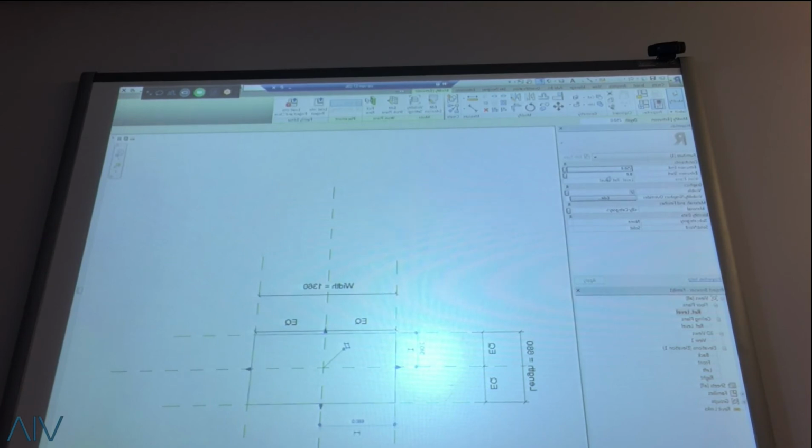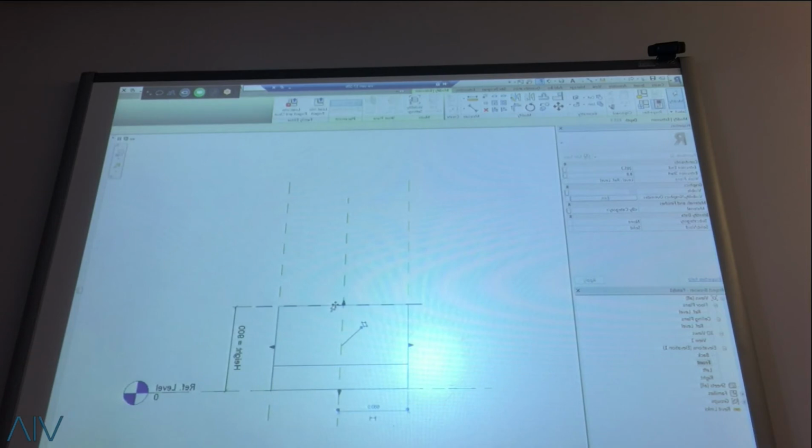Now, the next thing you want to do is the extrusion end. Here, you can just go in and say, okay, I want to stretch it and then just pin it. Just force it up and say pin it. I would do the same thing down below if you need to, but in most cases, if it's a family that you're not going to extend beyond reference level 1, you don't have to pin it.